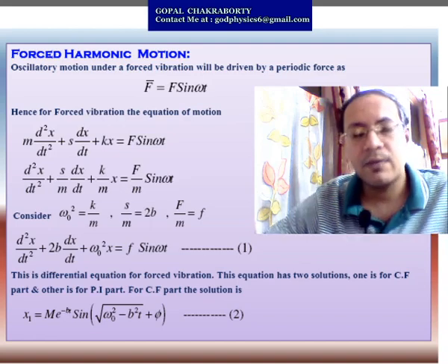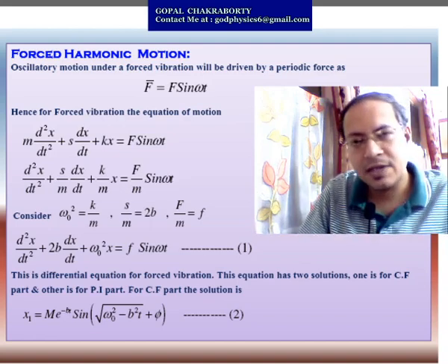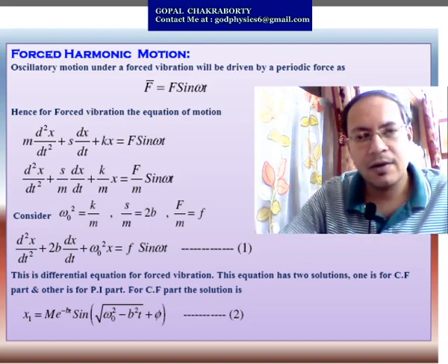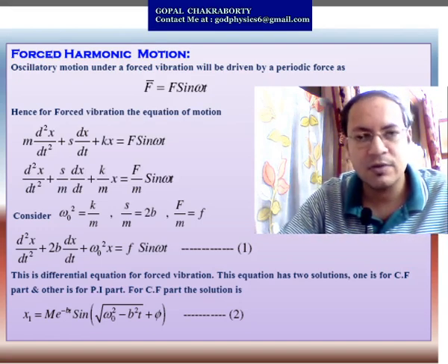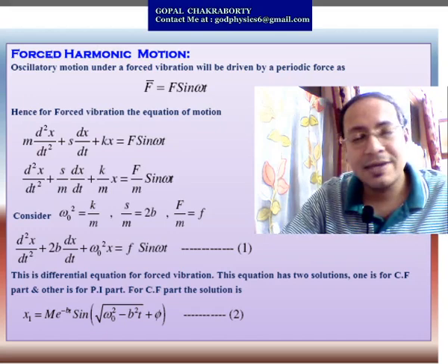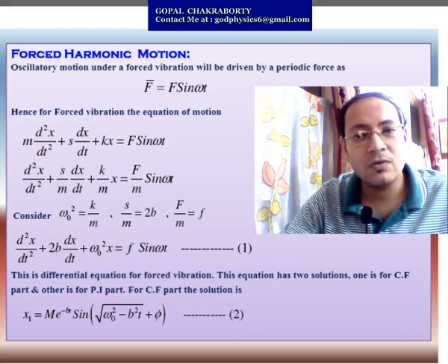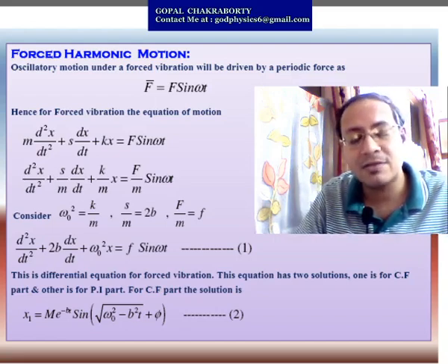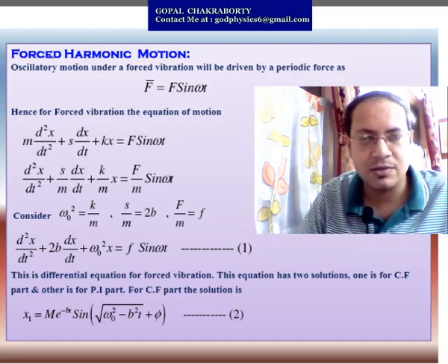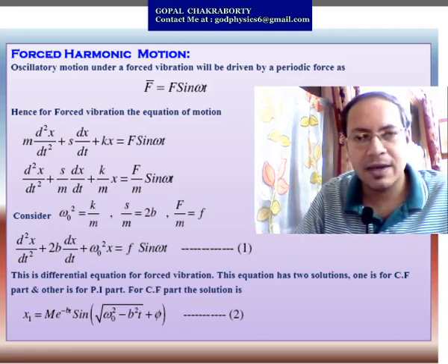Now I am going to derive the differential equation for damped vibration under forced vibration. I will show you step by step. Here I have considered a periodic force which is applied externally, that value is considered as F equals F sine omega t.